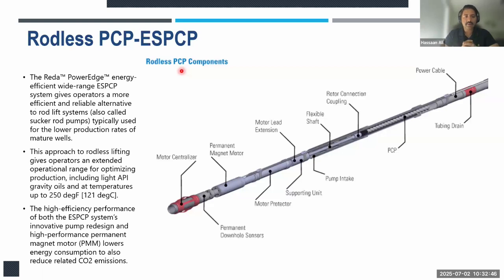But it is really good for the light oil API oils because now the elastomer has been selected in a way that it can dissipate that heat. There is something else in this as well, which I'm not going to go deep into, but the stator design is very specific for the light oil application, which helps to reduce hysteresis. That is part of that failure mode.